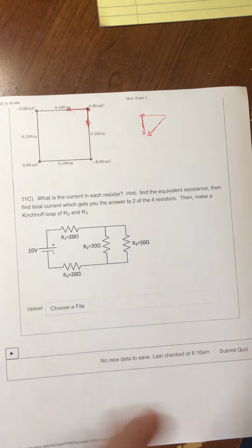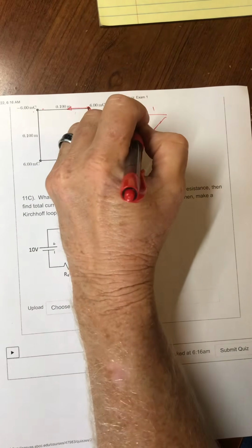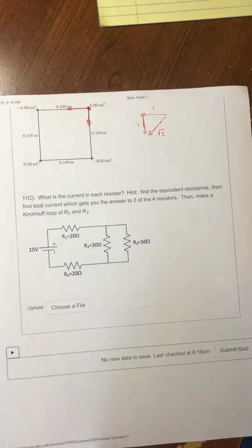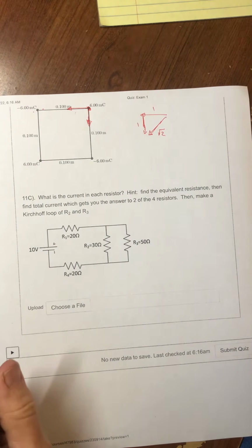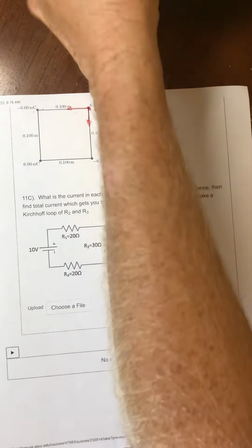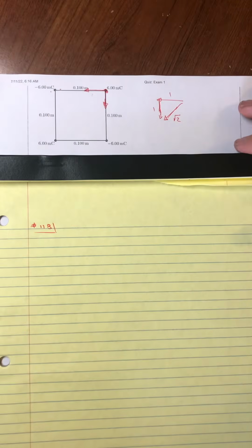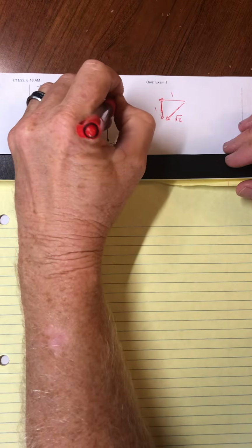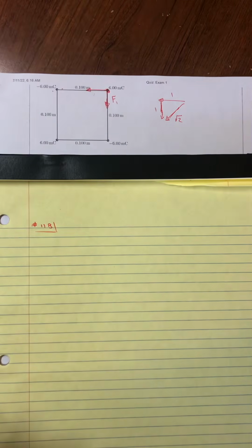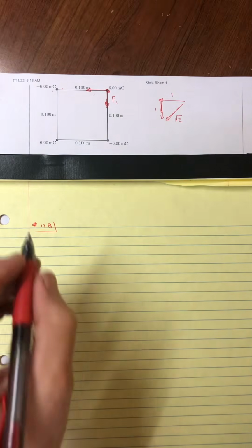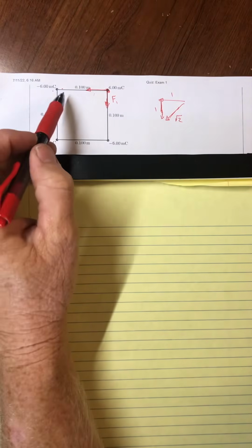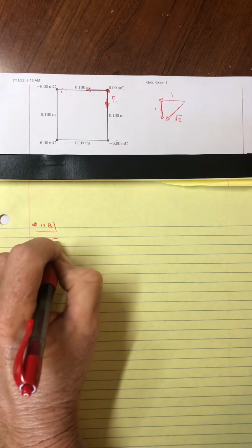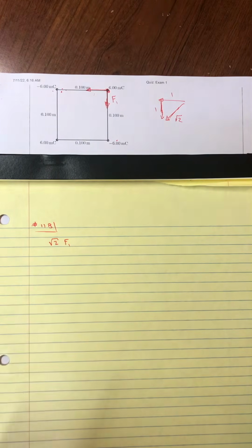Not only that, when you add them of the same length, so if you call that 1 and that 1, you might remember that the hypotenuse then is the square root of 2. And so we could take advantage of our symmetry by doing something like this. If we call this first one I was thinking about going down force number 1, then what we could say is the combination of these two would be the square root of 2 times the force number 1.